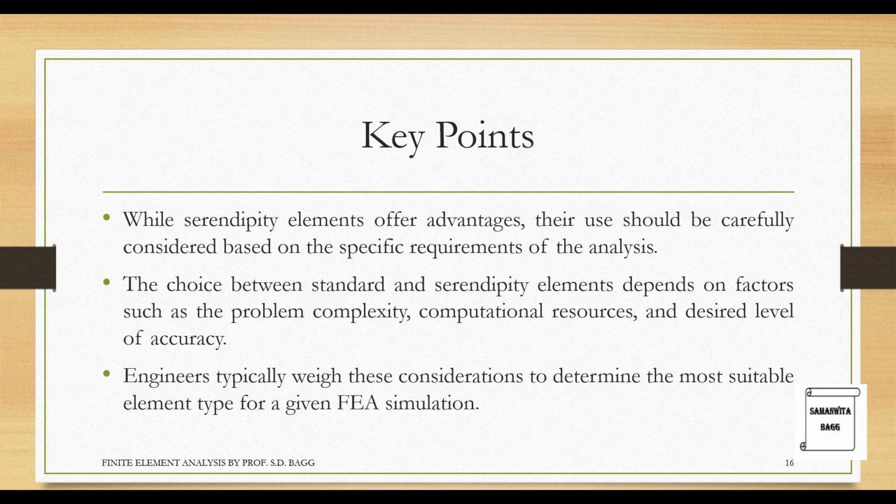So now some key points to take from this session. While serendipity elements offer advantages, their use should be carefully considered based on the specific requirements of the analysis. The choice between standard and serendipity elements depends on factors such as the problem complexity, computational resources, and desired level of accuracy. So if your problem complexity is not too much, then you can go for standard elements.